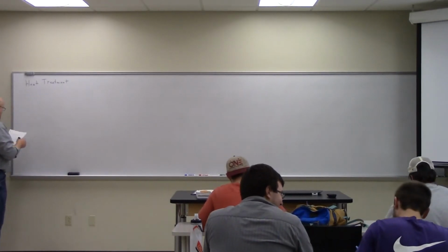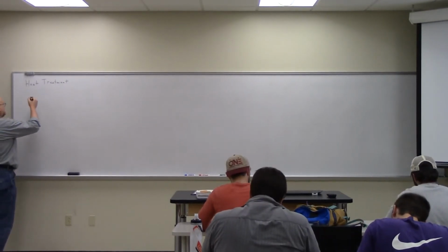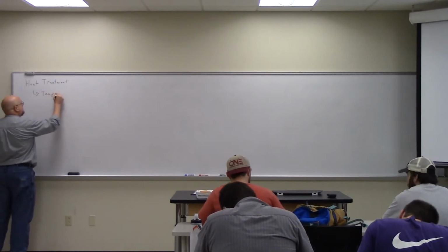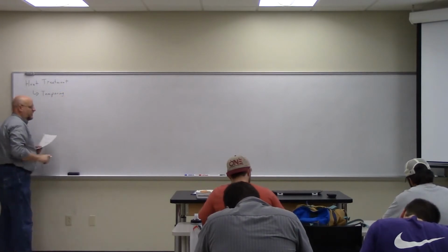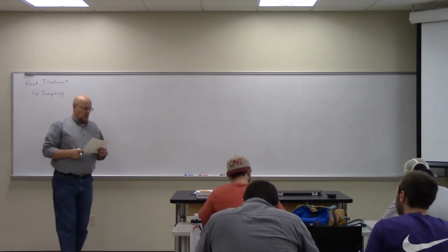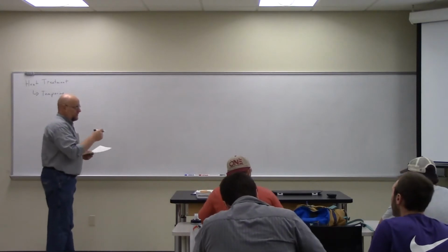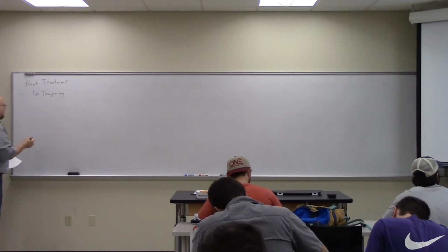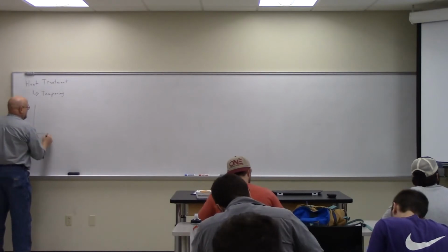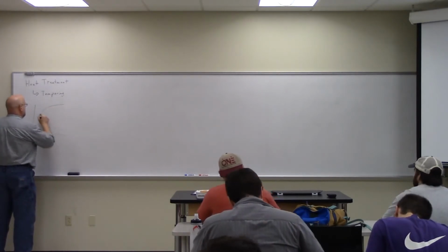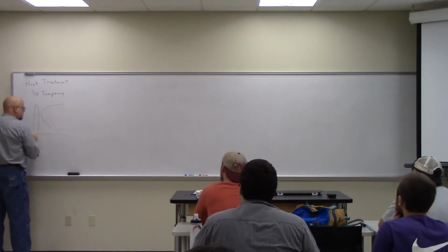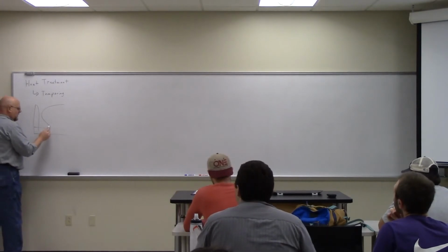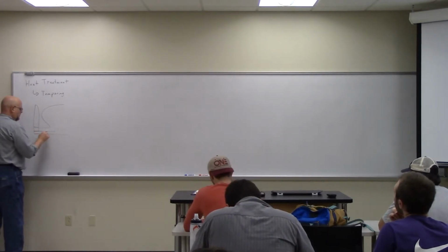Okay, so there are several different kinds of heat treatment. The first we're going to discuss is tempering. So, if you look at the TTT diagram for eutectoid steel, which is shown up there, which we drew before, we talked about the fact that if you can miss the knee in this curve, you can cool it fast enough down here to get through these martensitic transformation temperatures.